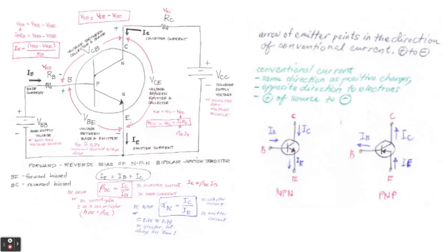Here, this is the summary of some formulas that we need to know in making sure that our NPN transistor or BJT is connected in the correct way to make it an amplifier. First of all, you have to consider the base to be connected on the positive side of the VBB, because this is P-type and this is positive. This will be in forward bias. If you are using PNP, so this is N-type, you should not connect it to positive. You must connect it to the negative if it is N-type base.